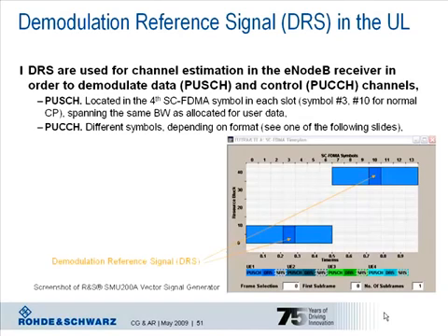The screenshot shows the time plan of the Rohde & Schwarz vector signal generator SMU200A, generating a 3GPP compliant uplink signal. 11 resource blocks are occupied and frequency hopping type 1 is applied to the signal. We can see that single carrier FDMA symbol number 3 in the first slot and symbol number 10 in the second slot carries the demodulation reference signal. If the UE would be assigned to transmit on fewer or more resource blocks, the demodulation reference signal would also be transmitted over these resource blocks. This is mandatory due to the nature of single carrier FDMA.